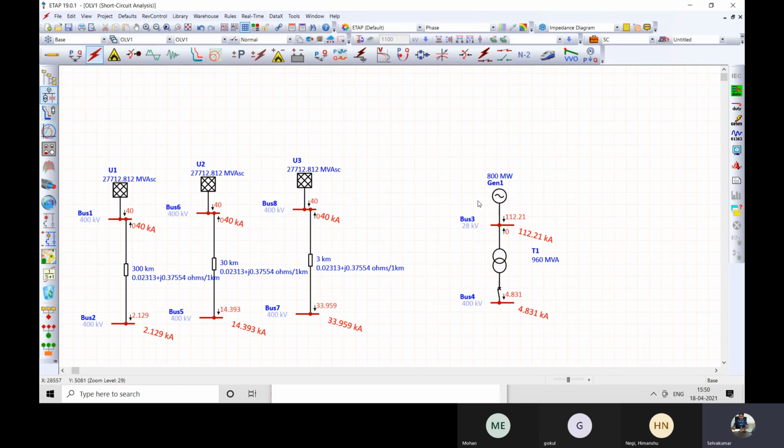But otherwise, when you have multiple transmission lines here, if the substation is connected with 20 substations, like you have shown in one of your documents, then that means it is a heavily interconnected system. By then the fault current will also be more. But when the fault current is more, the capacitance is also more. So there will not be any problem with the TRV.